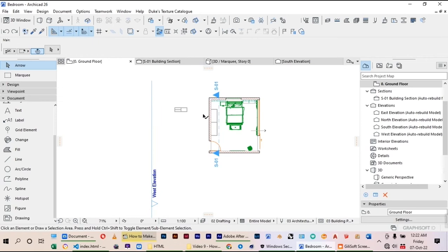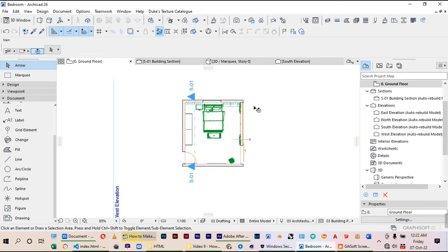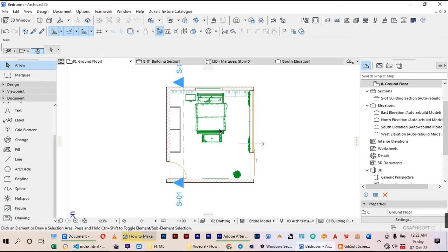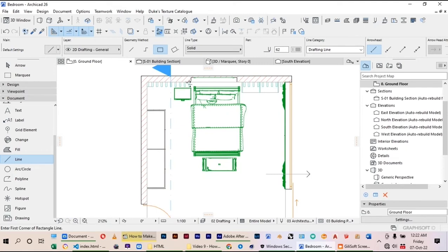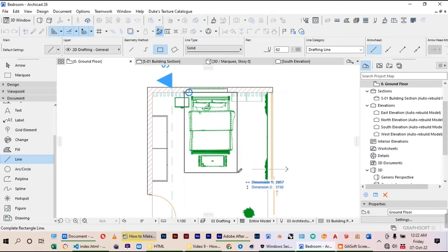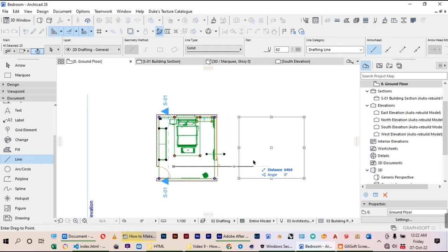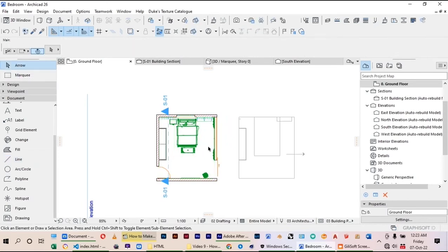Now, like I've already said, I like working with the Rhino. I've done the lines that define my space. Now I need an overhead above the bed. So I'll just come here and create the overhead that I want. Okay, and then let me remove the lines and take them outside. Control lines, Control A, Control D. Good, those are my lines.